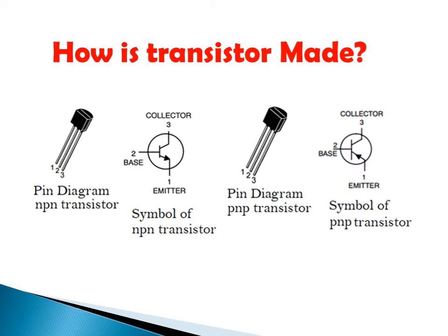If we treat silicon with impurities, a process known as doping, we can make it behave in a different way. If we dope silicon with the chemical elements arsenic, phosphorus, or antimony, the silicon gains some extra free electrons that can carry an electric current. So, electrons will flow out of it more naturally. Because electrons have a negative charge, silicon treated this way is referred to as N-type.